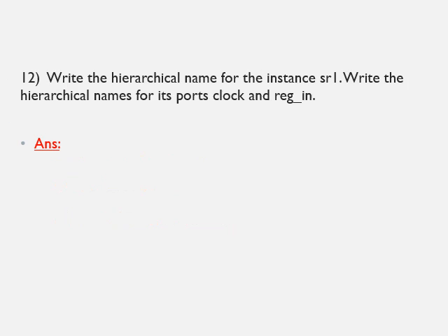Okay. Question number 12. Write the hierarchical name for the instance SR1. Write the hierarchical names for its ports, clock and register in. So here now the question is to write the hierarchical name for the instance SR1. Instance SR1 means this is an instance which is instantiated inside the stimulus module, that is the top level module.